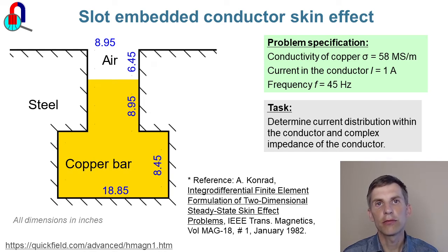When a rotor starts to rotate, the current frequency is high, and the rotor bar impedance is an important parameter that affects the torque value and the start dynamics. We assume that the steel permeability is infinitely high, so we replace the ferromagnetic slot with the boundary condition and set 0 tangential field component at the slot boundary. And we also assume that the field is contained within the slot, so we will set the boundary condition at the top.